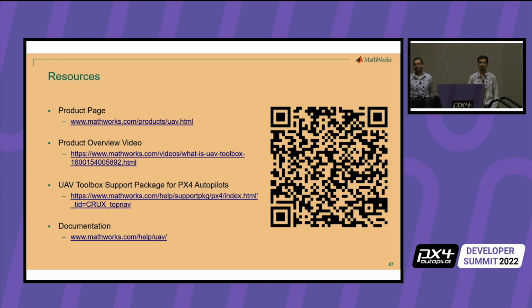Normally, how would people go about creating a new environment for their own research? You would start with an Unreal project. Unreal Engine lets you open up a project and start putting in meshes or buildings. A lot of assets are available for free, so you can start building a world with them. You can also buy these. People build Unreal environments and sell them. So if you find something really nice, you can buy it and link it to Simulink. You just point it to the path of where you put it, and that environment will open up.